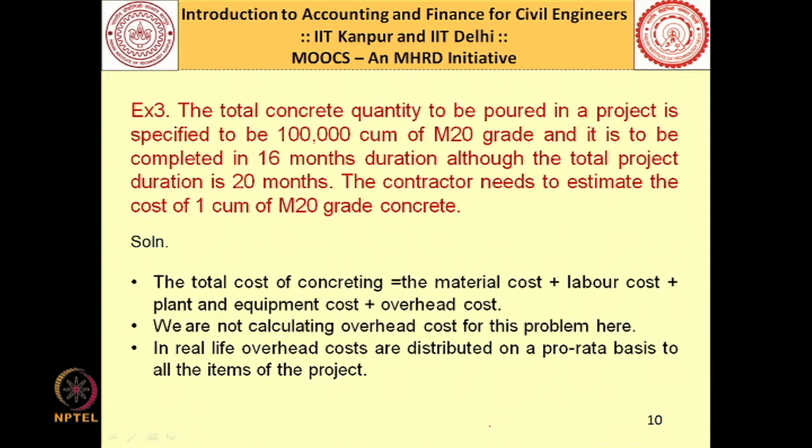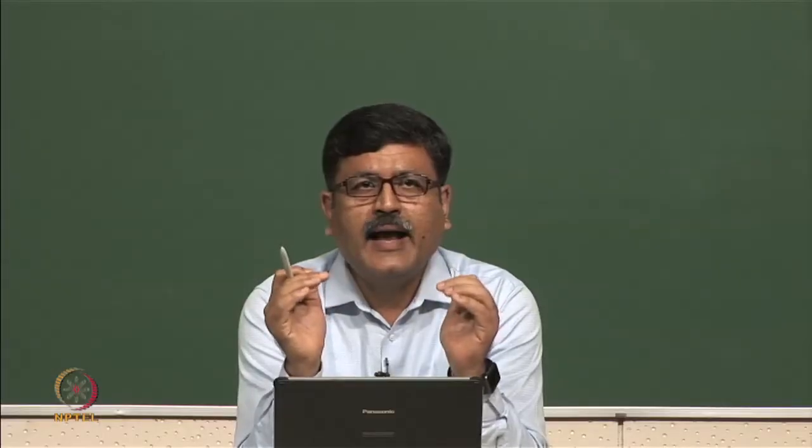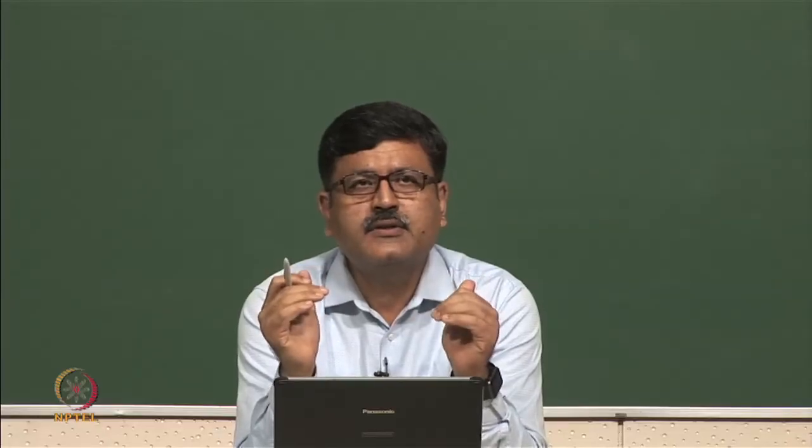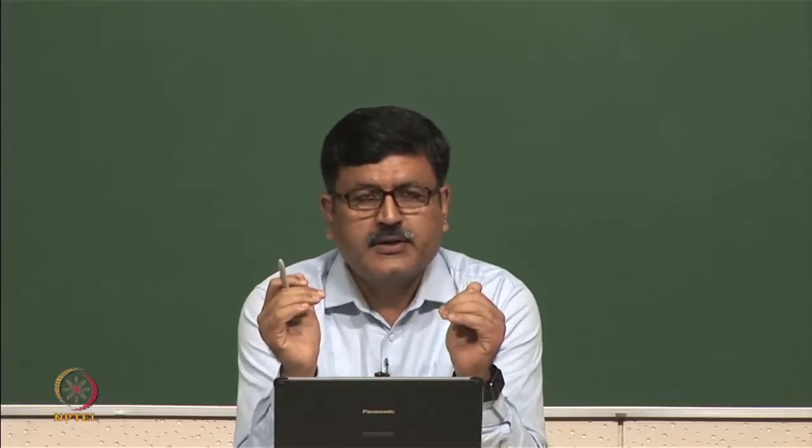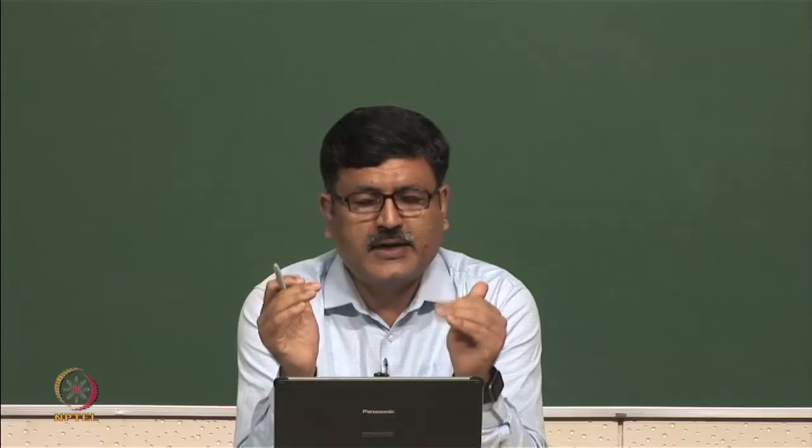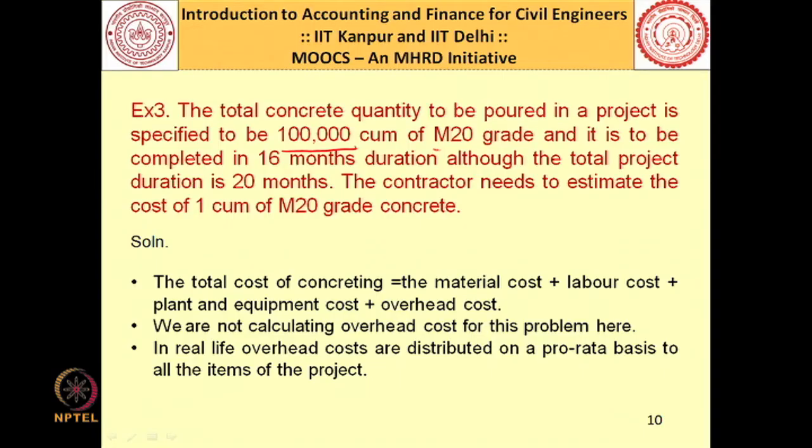Now, I will illustrate some other method. So far you have studied how to carry out the unit rate analysis. Now, we will see how to carry out the operational estimation process. Now, in operational estimation process, all the time we have to consider the time frame. What is the duration and what is the quantity in which it has to be performed. So, in order to reflect these two aspects, I have given you a small problem.